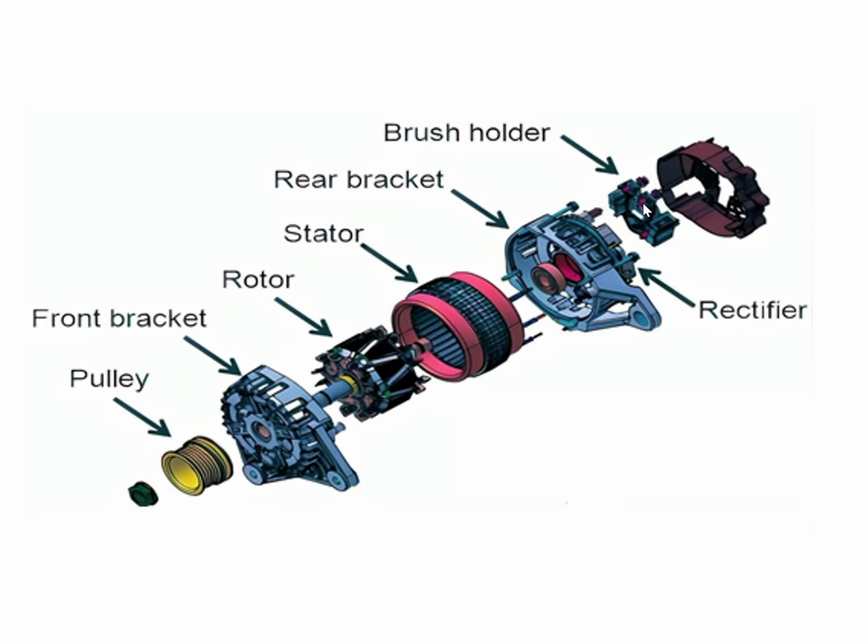We have seen about slip rings in the previous slide. For single phase alternator, two slip rings are there. To get communication between the internal parts of the winding of the machine with the external circuitry, we need brushes, carbon brushes, connected with that slip ring. For that, carbon brushes are to be placed within this brush holder. So rectifier part is here.